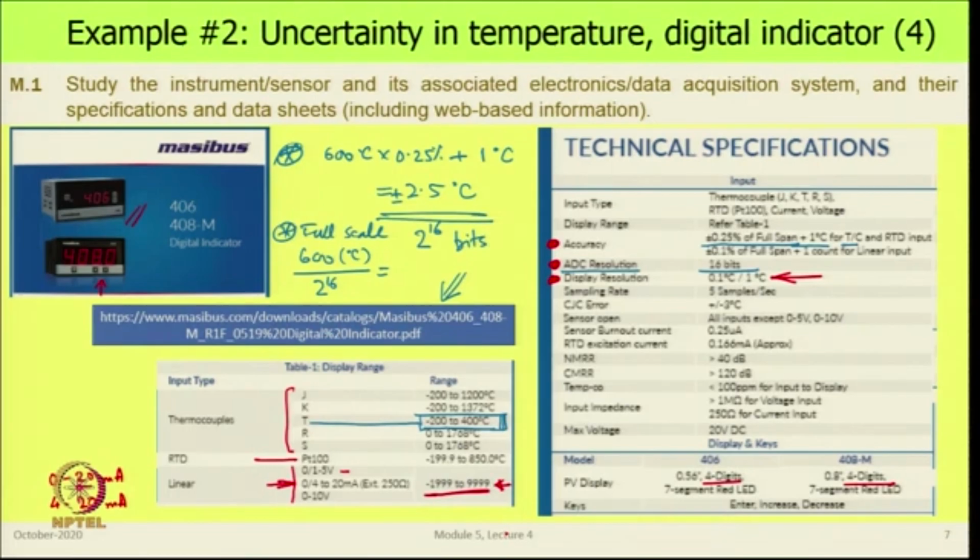So, if the temperature indicator was transmitting a current signal, we would use this. What we will do is directly connect our temperature sensor to this indicator and see what happens. So, we are not wanting to get into this part for now. But in the real world, this is how things will happen. One will have to work with one of these things because the distances would be long. You do not want signal attenuation, and so that is what you do.